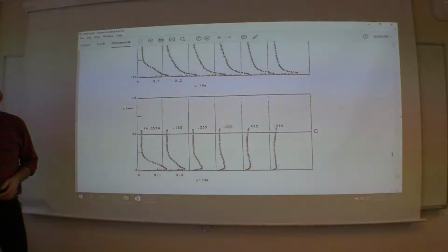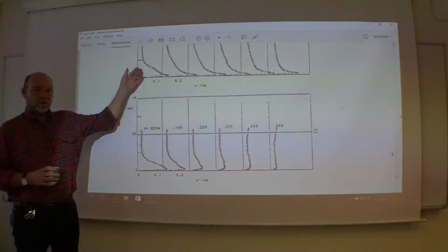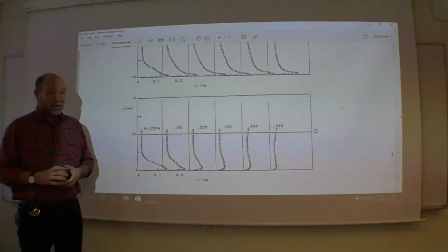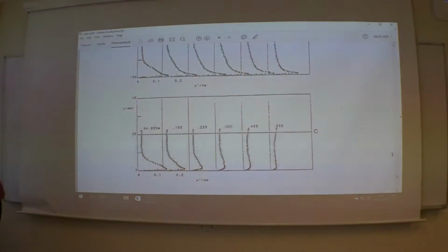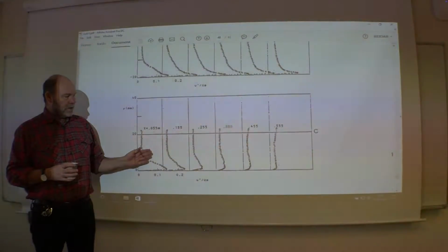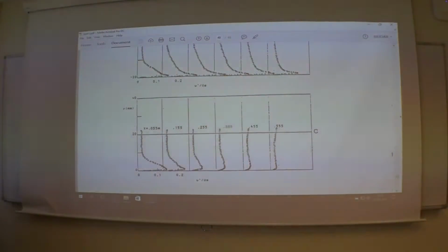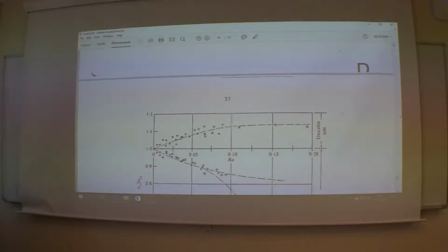So these are measurements, and if you try to simulate this with a K epsilon model, you wouldn't see a difference. It will give you exactly the same on each side, which is clearly wrong. Of course, you can find K epsilon models and K omega models that have some additional terms, trying to take into account these rotational effects. So yes, they exist, but you have to be aware of them.